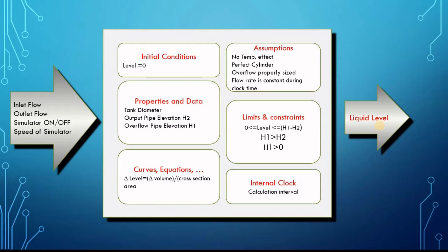If you have a pump, let's say a variable speed pump, your data input is the speed command, the resistance of the line or the process profile, and maybe the inlet pressure to the pump. And then what is your output? Do you want to know the flow and the pressure of the pump? So you have to define what you want to do.